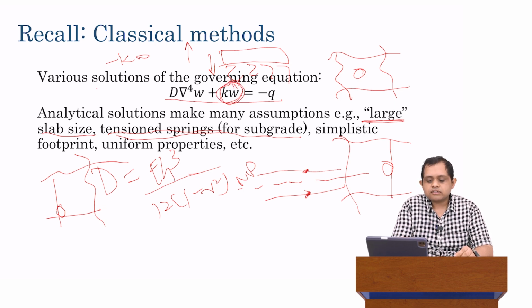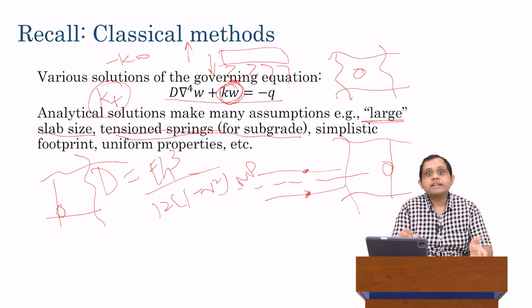So we actually write it typically like this, K plus, that we only allow springs to be in compression, and when springs are in tension, we assume that K is equal to 0. That's what this K plus symbol means. We cannot analyze that technique using analytical methods. It actually becomes a nonlinear system of equations in that case. So we can't actually solve this technique using analytical methods.